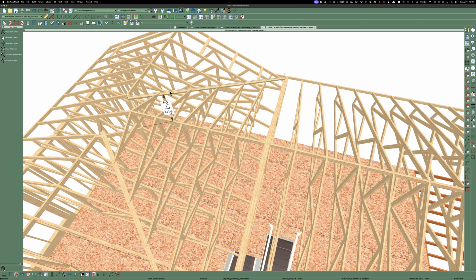These have to be bigger. Like if you're stick framing this and not putting trusses down, you need to have a 2x12 just because the seat cut is going to be so long, and the entire seat cut has to be supported. And I've done some of these lower pitch roofs, like I think this is a 5, where you do the 2x12, you plane across here, you use your calibrated eyeball, you look across, and when the tip edge of this can be seen at the top and the bottom, you nail it.